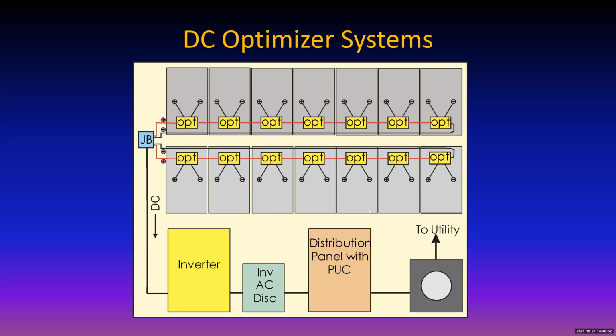Does a combiner filter harmonics? No, the inverters themselves do their own filtering. So the output of the inverter is very, very clean. The combiner just combines the outputs because you got a bunch of like 5,000 watts or so at a time. And if you want 20,000 watts, you might have 4 of these strings in parallel. So that's what the combiner is.